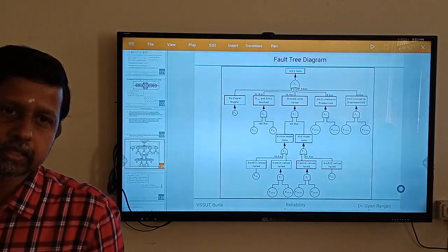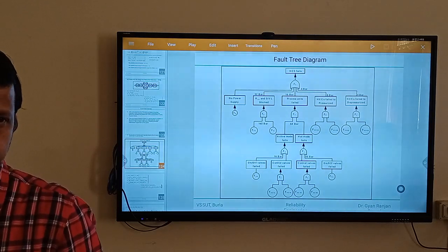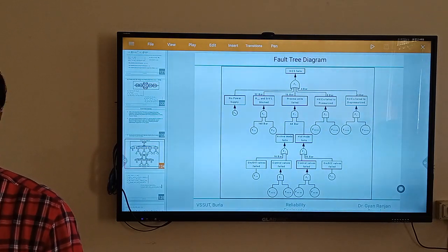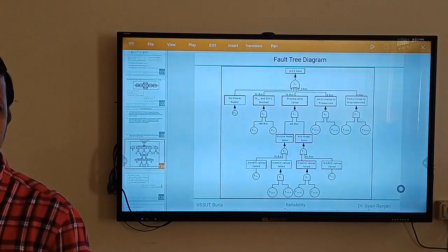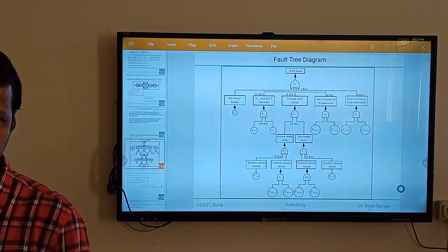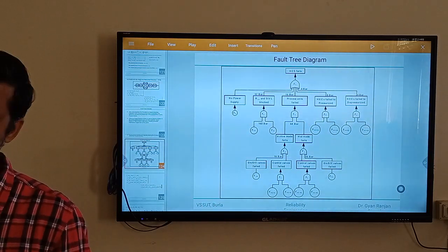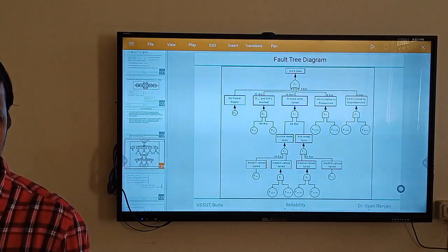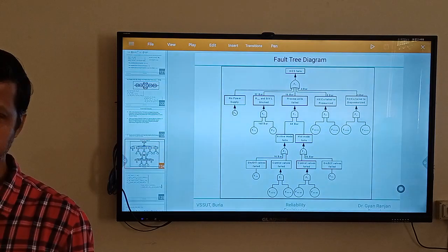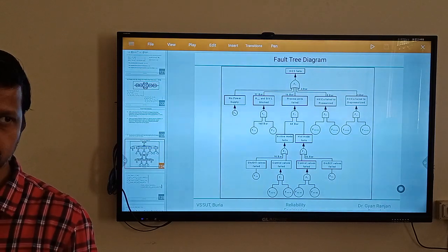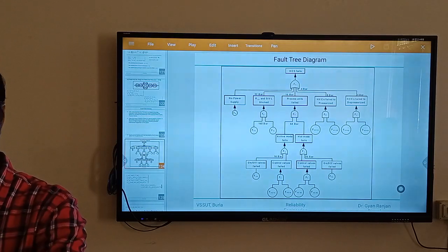and the current amplitude is 30 ampere, 40 ampere, 50 ampere, 60 amperes, huge. What will be the power dissipation? I square R. Imagine the kind of heat it is dissipating. Okay? So you need to dissipate those things from the stator and rotor sections. Now the rotor section is itself dynamic, you cannot do anything. At least in the stator section you can keep those arrangements, and you might have seen that there is actually a water pipeline. So we flow the chilled water inside the pipe.